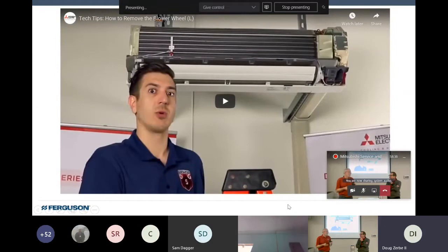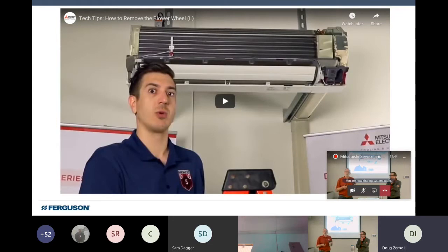Mitsubishi has a website with many videos available. They're called Tech Tips, and this is one of them. The easiest way to clean that blower wheel is to actually pull it out, take it outside, hose it off with a high pressure nozzle, not super high pressure, clean it out, let it dry, and then reinstall it. In this 2-minute video, we're going to let him show us how it's done. It may not be exactly the same for every unit, but the basics are there.